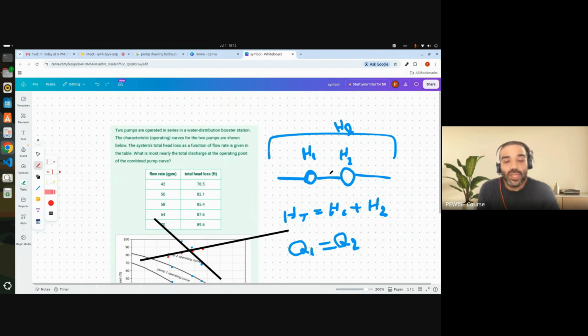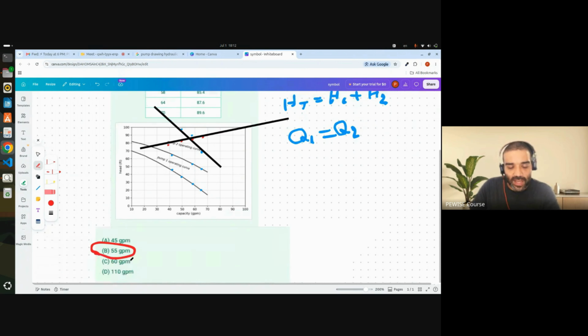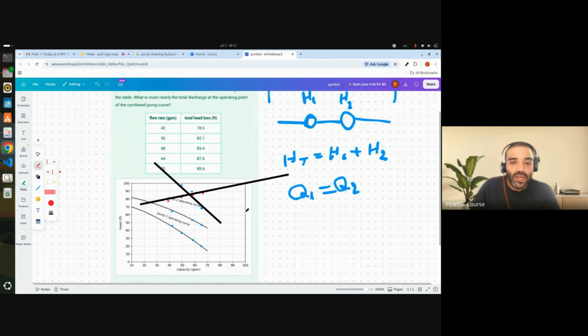At the same time, by increasing capacity, the head loss increases. So these two have an equilibrium, and that's the capacity that you get out of a system. The rest is just drawing the points on the chart and finding the intersection. Usually they give the values in a way that being wrong by a little bit doesn't hurt. You can find your answer in the options.